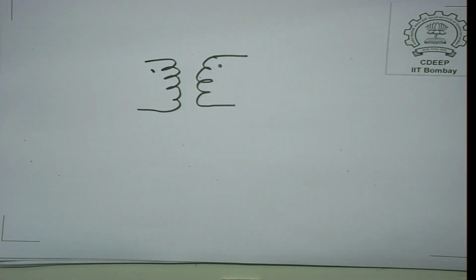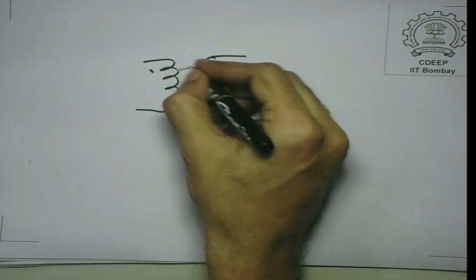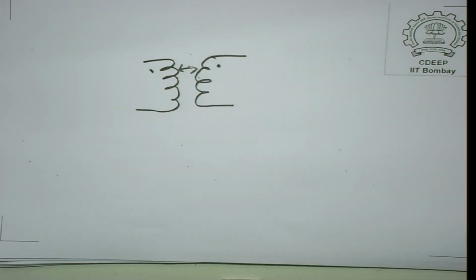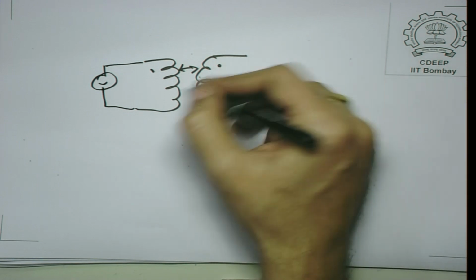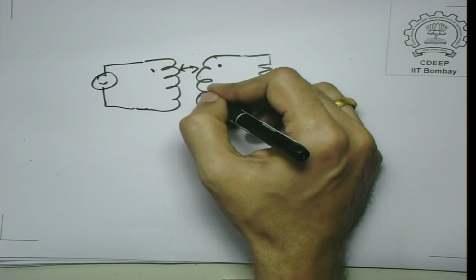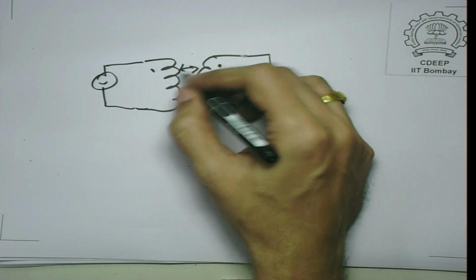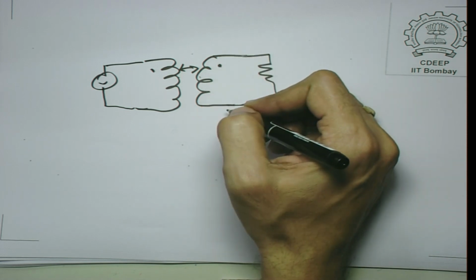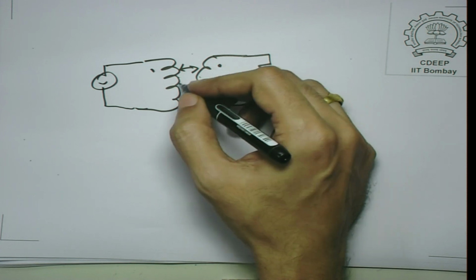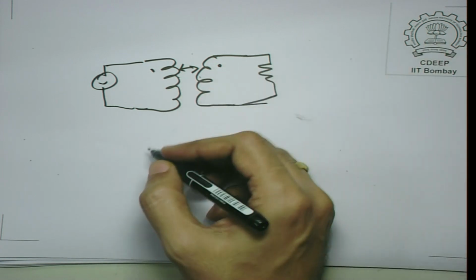So, there is the insulation resistance and the intra-turn capacitances which are there between the windings. Okay. So, there is a kind of capacitance between these two windings and also the insulation resistance. So, there is an impedance between the windings which is very high. So, actually there need not be any current flow between these two. So, if you have got, say, a sinusoidal source here and a load here, actually no current traverses this because this impedance is very high. Only due to induction the voltage is induced and a current flows here. Okay. So, there is no direct conductive coupling between these two sides, and this is very useful because what it means is that